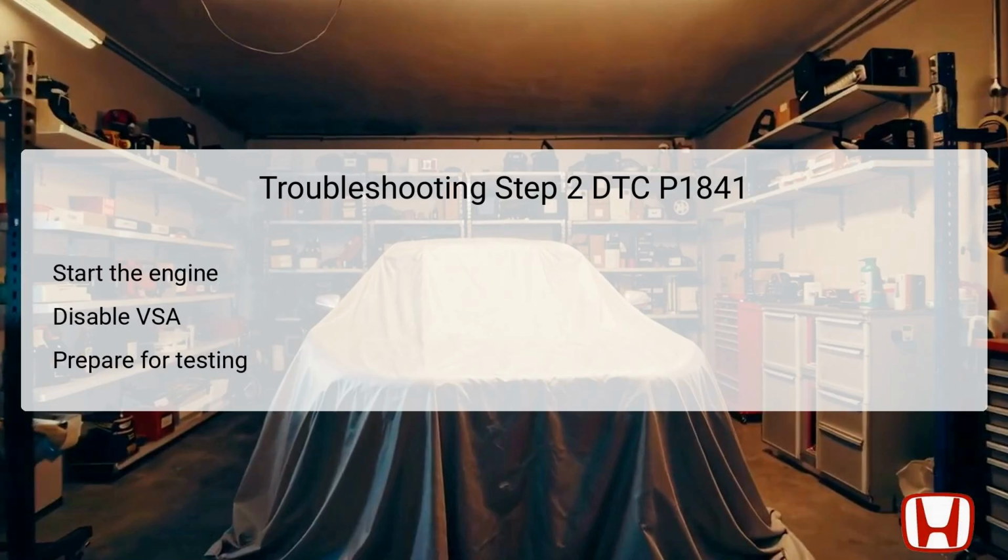Next, after safely securing the vehicle, the technician must start the engine to allow the system to enter an operational state. Disabling the VSA, Vehicle Stability Assist, is crucial during this step, as it can interfere with the readings and testing conditions necessary for accurate diagnosis.